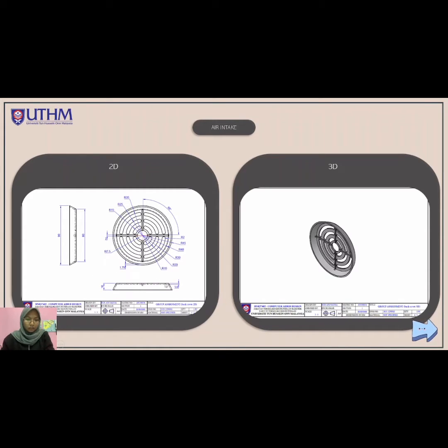After that, on the top of the 40 millimeter circle, I use a line. The length is 80 millimeters. I divide it into 4 parts. After that, I drew these rectangles, 4 rectangles. The length is 32.5 and the width is 2 millimeters.